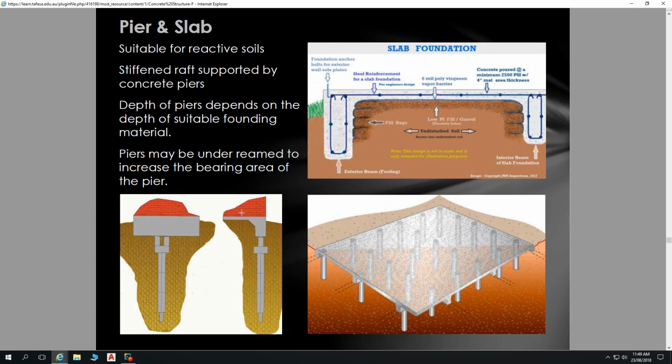Or you can auger out earth and fill that with concrete to create piers. And there's even a thing called bell piles. I mentioned bell piles before. That's where you've got an auger that digs a hole and has a bit that flicks out. So you dig a hole, and then it's able to scrape this earth out and get that out. So you've got a pier that has a bigger footing, so better bearing onto the soil, but then also locks that pier into that soil as well.